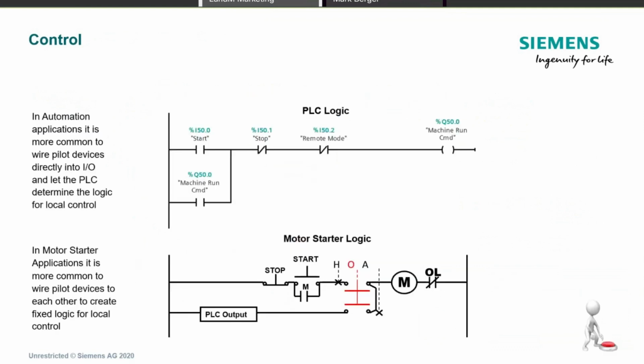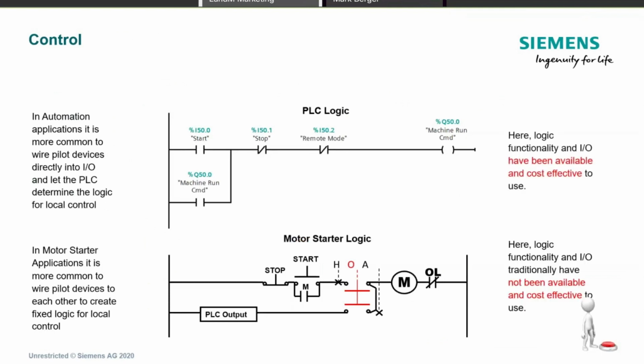Here's just a standard HOA circuit that you may see in the PLC. You have your standard hand-off-auto, start, stop. And then you have these contacts here, your motor verify, and it is your interlock or your sealing circuit to keep the motor running once you push start. And here's some of the logic that you see. Here's that sealing circuit over here. The right motor management system can change the equation of all this.